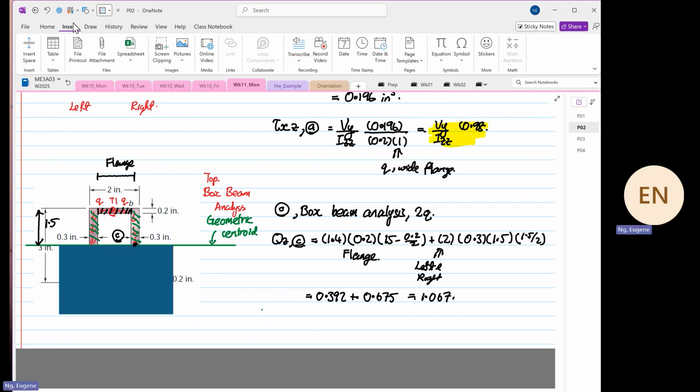And then we substitute in now the shear intersecting the x plane. However, the direction is in the y direction, right? Because if you look at Q down here, Q is flowing vertically down, which corresponds to the y direction. Over here, Q is in the horizontal direction, so it's in the z direction. Okay.